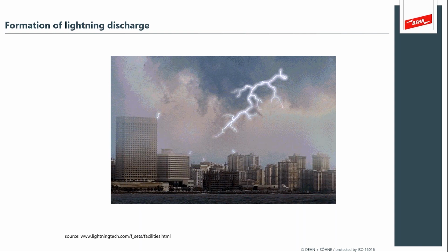And as lightning propagates, the final step leader initiates the complete return stroke, and now the charge moves through the atmosphere. And what we understand, of course, is that charge is moving only in one direction. Although it's a fast pulse, it's a single direction. It's like a big DC event. And what's interesting is the fact that, as I mentioned, it isn't one single attachment point. Everything in the influence of that electric field is trying to reach out to that lightning stroke.